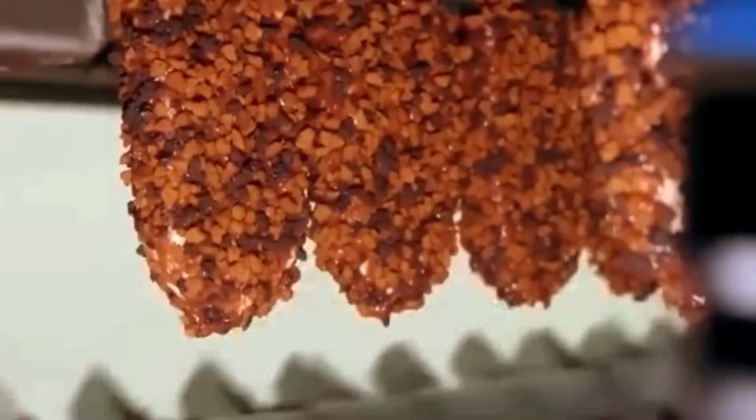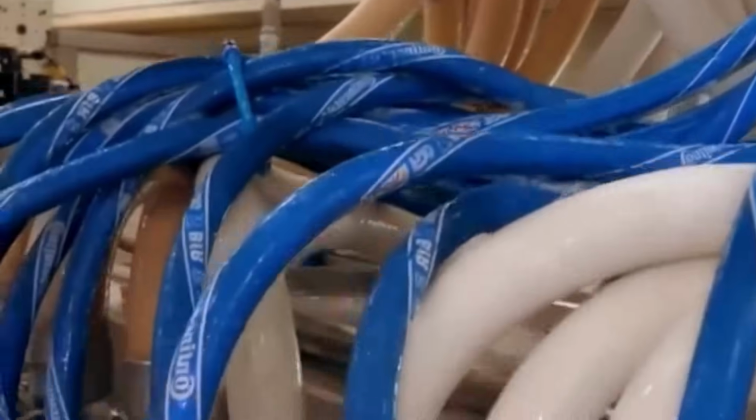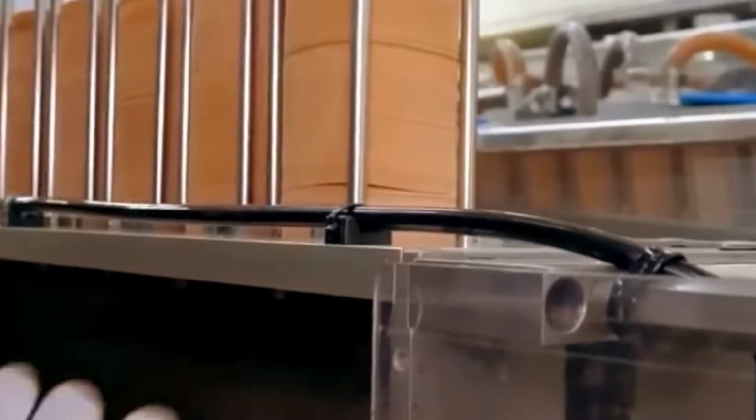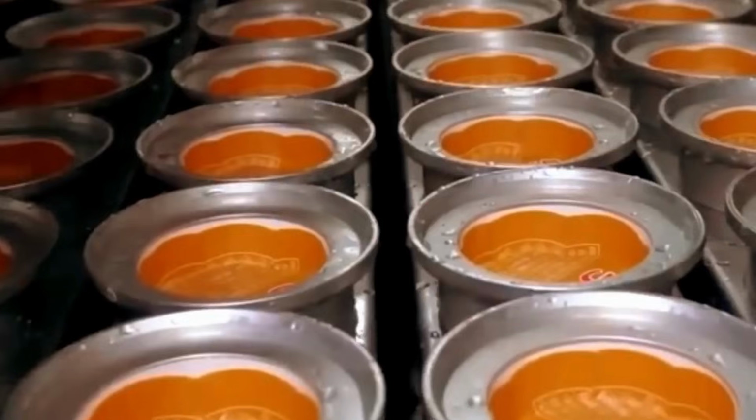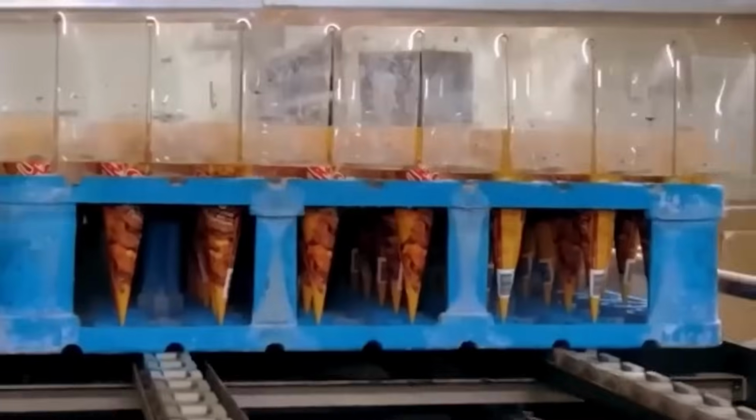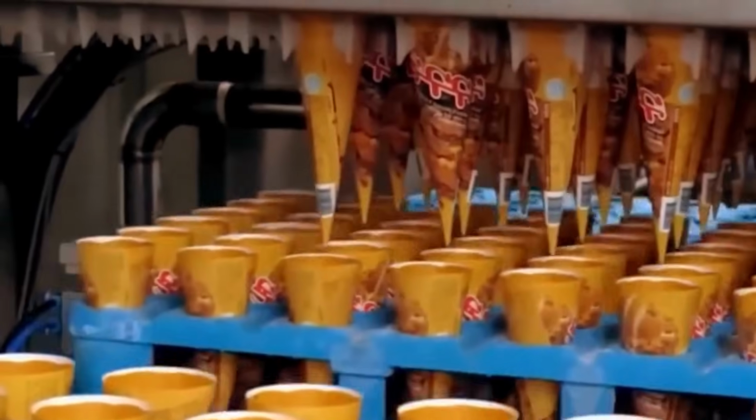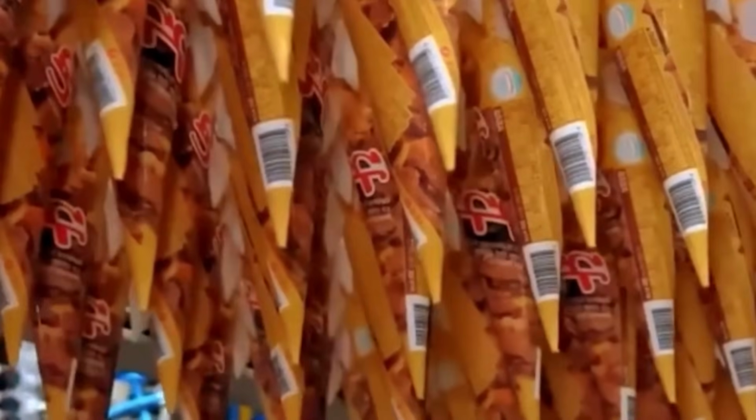After inspection, individual packages are sorted into multi-packs or cartons using robotic collators and carton erectors. Units are loaded into retail-ready boxes, sealed with glue or tape, and labeled with barcode identifiers. Cartons are stacked by robotic palletizers into programmed patterns based on load configuration and distribution route. Stretch wrapping machines secure pallets with film before warehouse transfer.